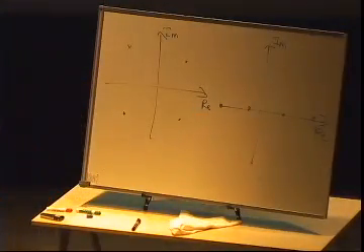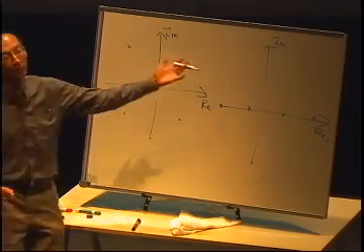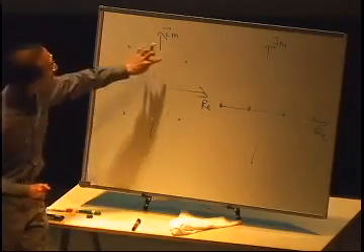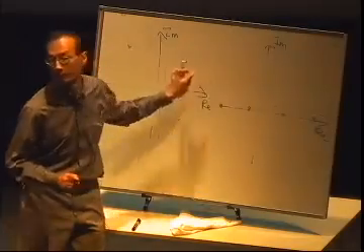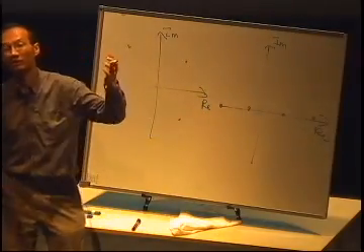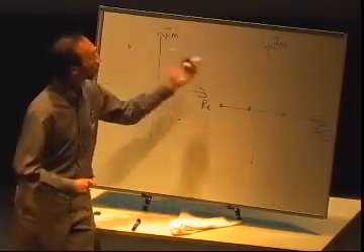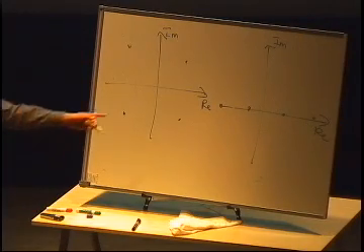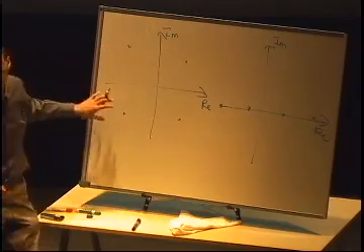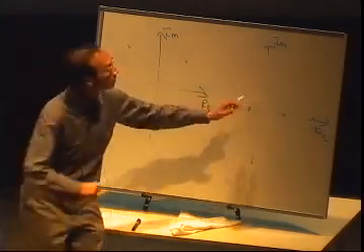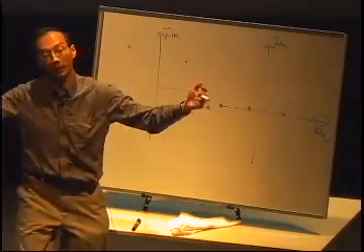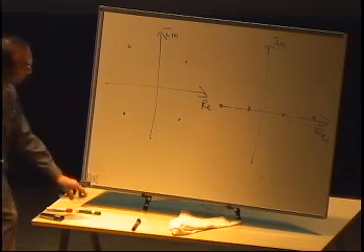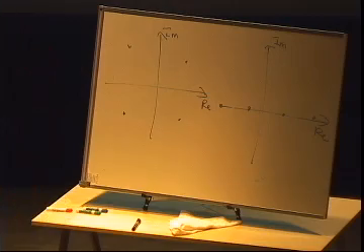Okay? All right? If I want to make sure the error probability is the same in the 2 cases, essentially what I want is to make sure that the nearest distance between these points is the same in these 2 cases. Right? If the nearest distances are the same, then I can ask the question, which one uses more power? The PAM uses more power. You can see from the picture, right? Here I have 2 dimensions to put these points on. Here I only have 1 dimension, so as a result, I have to make it longer, further away, more power. So QPSK is more efficient. In fact, the calculation says that I need 4 dB more transmit power.